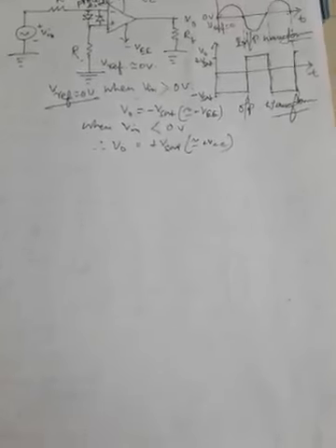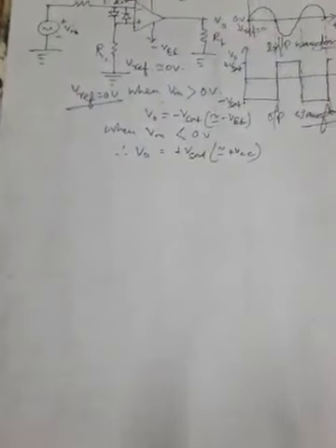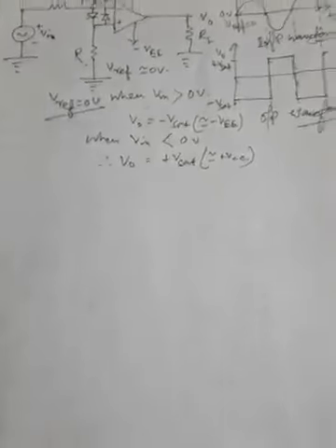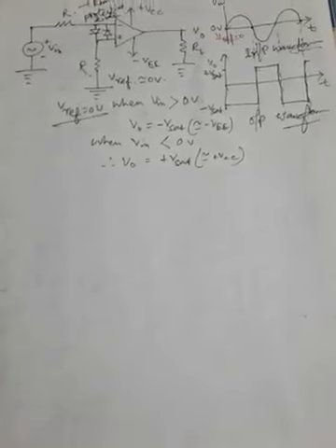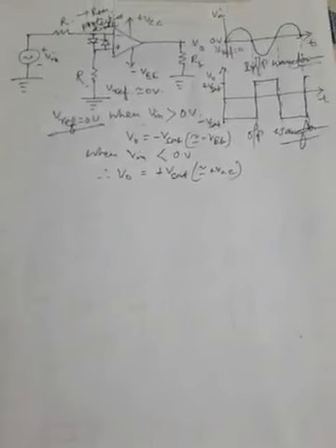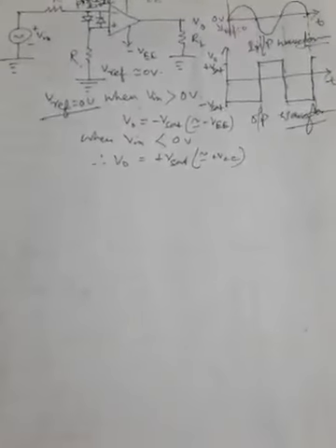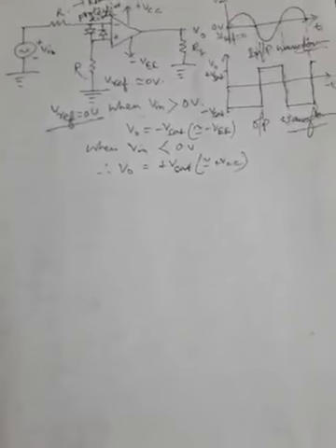Detecting zero reference crossings for noise voltages also. So when noise is present, the detection of zero crossing may be based on both V in and the noise voltage. Because the two types of voltage, V in and noise voltage, are both applied at the input of the op-amp, there will be two types of zero crossing detection, and as a result the switching between the two saturation levels may become faster. Or in other words, the noise voltage triggering will be a false triggering. That means it will be a false switching between the saturation levels if noise is detected for zero crossing.